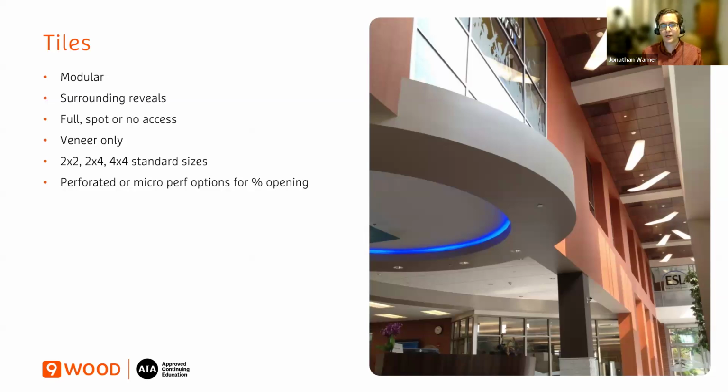And in terms of NRCs, sound absorption, it's really going to come in two ways. One is a perforated or microperf. So perforated has much larger holes that allow the sound to go through the panel. So it can be like a 1/4 inch or an 1/8 of an inch hole, very visible, even from this height as shown in the photo. A microperf has very tiny holes that enable sound to still go through and achieve good sound absorption. And so if you need sound absorption and you want a tile, ask your manufacturer for both options. You want the sound absorption, but you want it to look like a tile without the perfs, and the microperf is the way to go for sure.